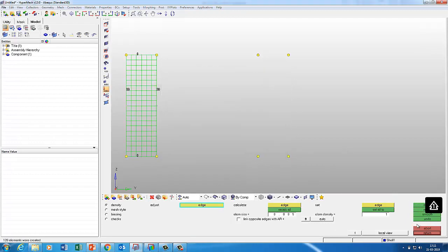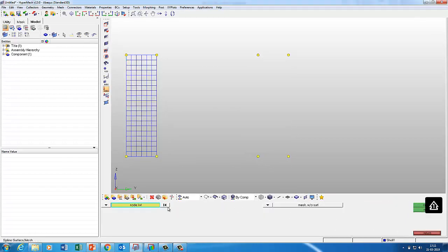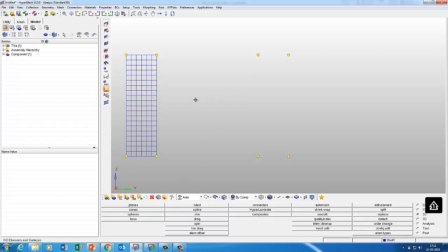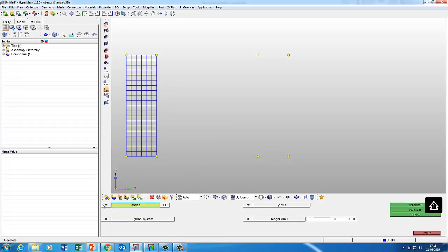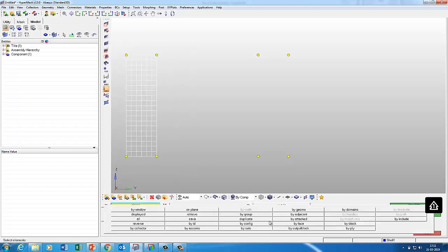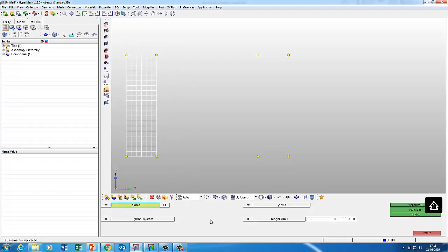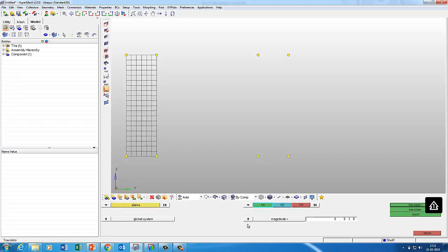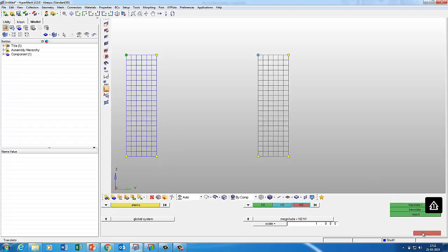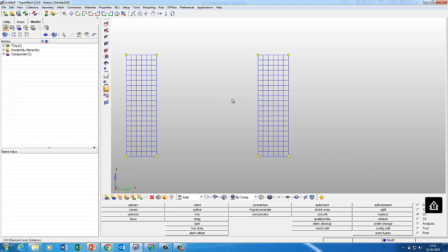So we put a mesh for that. I'll just copy this mesh to the other end. So Shift F4, I select all this element, duplicate original component, and here I'll say N1, N2, and I'll say move this to this. So we don't have to really go and mesh it. So we got all the insulation thickness.